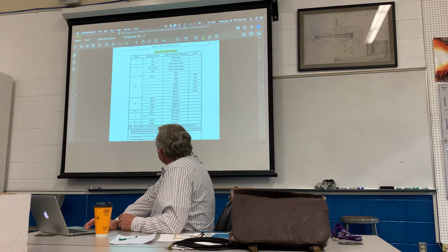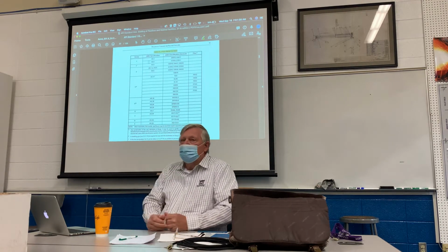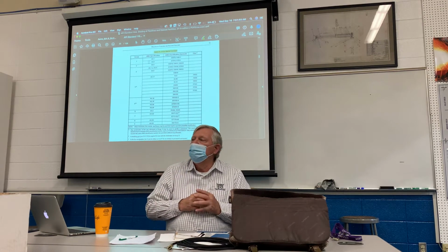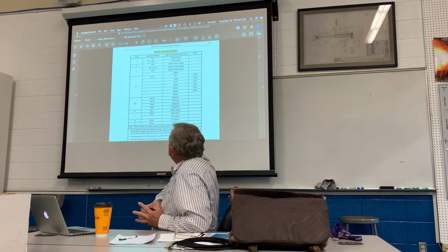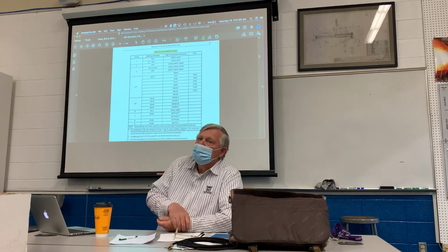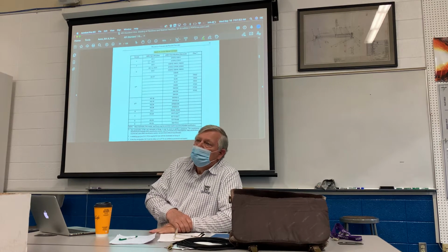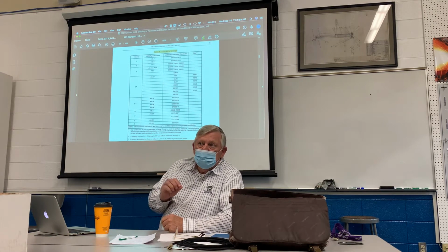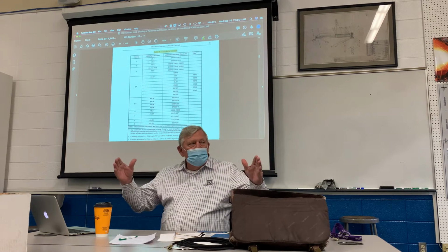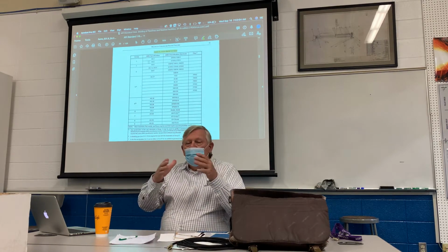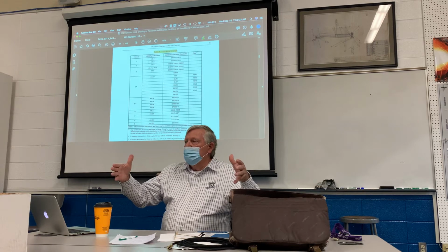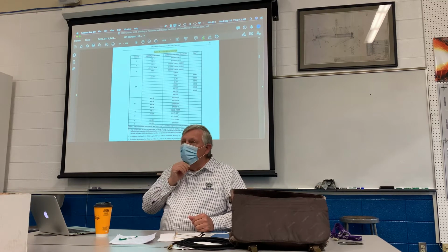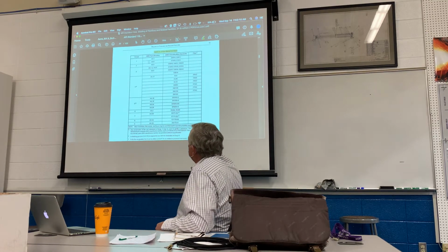specification though. So if you go back to the procedure, and you see your specification on the procedure is 5.1, can you switch to a 7010? No, because you have a different specification. That's an AWS specification that spells out the quality and the manufacturing processes that they make those with. 5.5 is a higher level. So 5.1 is a lower level of quality, and it gives us a different kind of a rod.